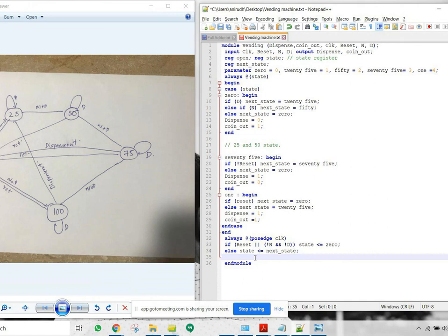If you don't want that, remove that direct path between 0 and 100. Otherwise, in your case, there will be two inputs. 25 cents is one input and dollar bill is another input. So you either change the state diagram or you change the design, depending on how you want to make it work. Zero state should have an arrow showing reset.